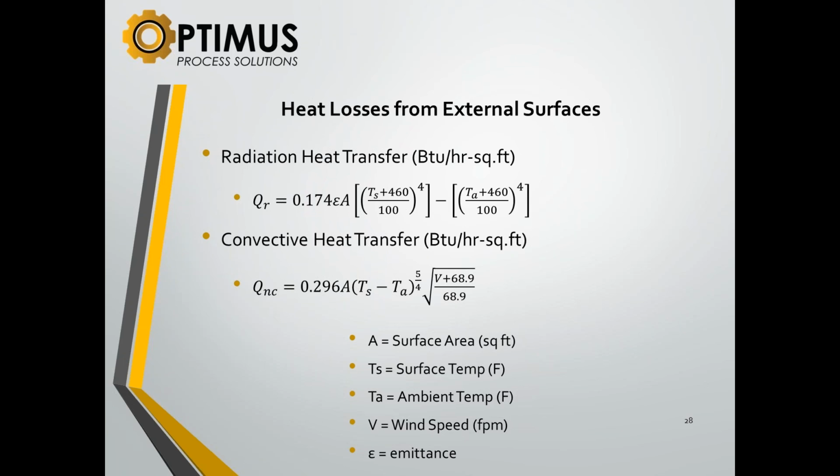And then compare it to the IR. Compare it to the IR to get an idea, because you want to get this right. So what you're saying is if you just go up and use your infrared gun and just click it and get a temperature, that might not necessarily be right, because of the emissivity. If it's a shiny surface versus a rusty surface, most kilns have a rusted surface. So like a tire versus the shell, just the emissivity can give you differences.